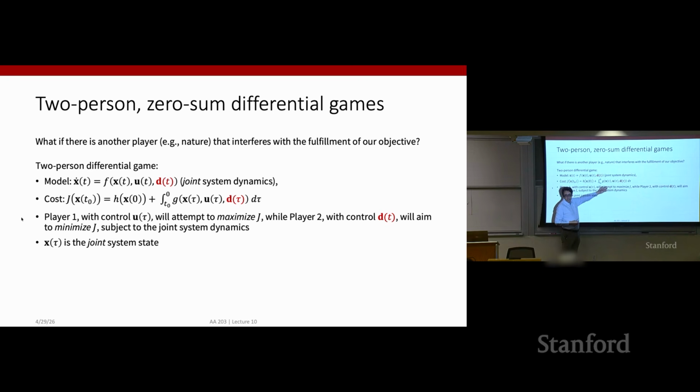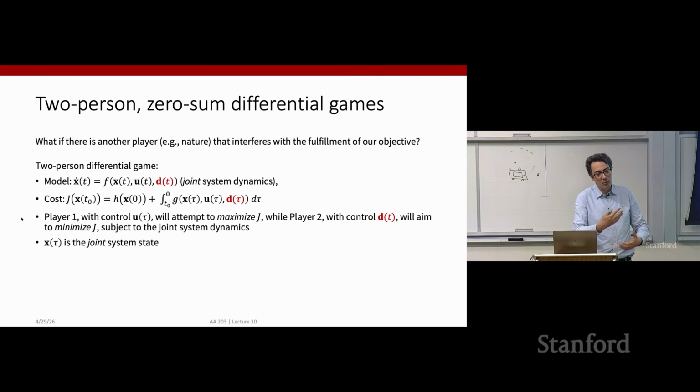But you could also consider a stochastic formulation. Actually, ACAS-X, which is the next generation collision avoidance system, is built upon a stochastic formulation. And then, of course, you can capture some notion of adversarial behavior through the probability distribution that defines the realization of the random variable. These are different modeling choices.